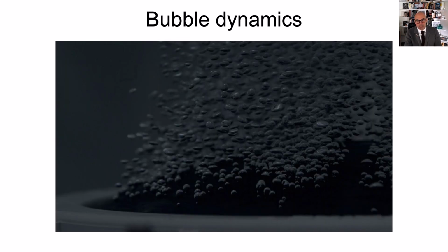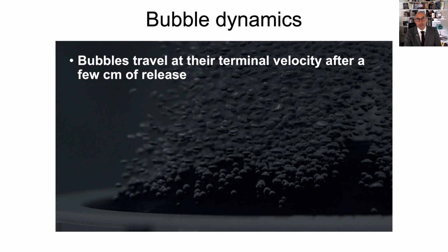So bubbles could be small, could be large. The picture here shows small bubbles being released by a fine pore diffuser. Now, the bubbles are released, and if there is more pressure in the air inside than the hydrostatic head plus the pressure drop, the bubbles are released with an initial velocity. So the bubbles are released in a jet area, and after the jet zone, the initial velocity is dissipated, they slow down, and eventually reach their terminal velocity, and they keep wobbling about in a plume.